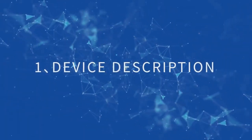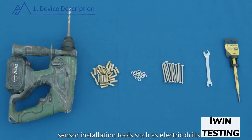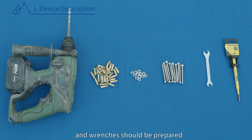1. Device Description. PDA host, high-strain testing cable, strain transducer, piezoelectric accelerometer. In addition to the host and supporting accessories, sensor installation tools such as electric drills, expansion bolts, and wrenches should be prepared for high-strain PDA testing of foundation piles.